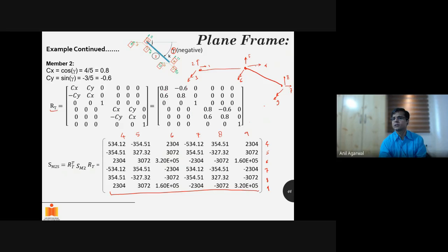Because when you introduce a unit deformation in the 4th degree of freedom, in this direction, it introduces axial behavior, an axial response from the member. It also introduces a flexural response from the member. So 4 and 5, likewise, when you introduce 5, it is partly axial. That is basically if the member stretches or this joint moves by a unit here, it will be extending a little and it will also be flexing a little. Likewise for 4. So now what you are getting is 4 and 5 are coupled. They are not uncoupled anymore. Okay, it makes sense, right?